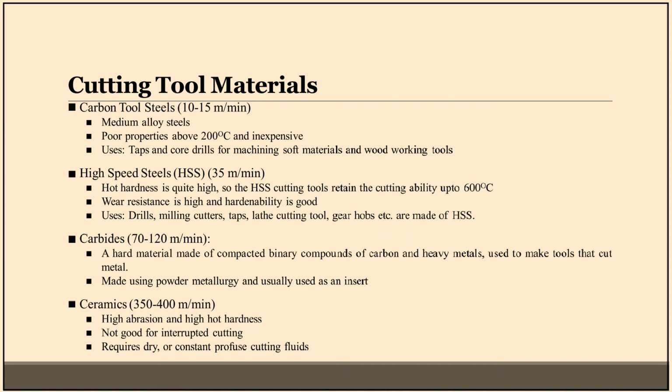Last one is ceramics, 350 to 400 meters per minute. High abrasion resistance and high hot hardness. Not good for interrupted cutting. Requires dry cutting or constant profuse cutting fluids.